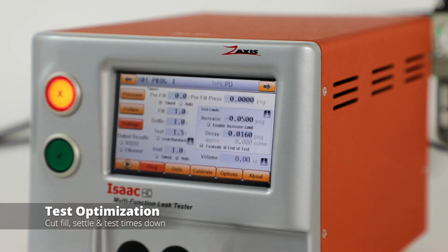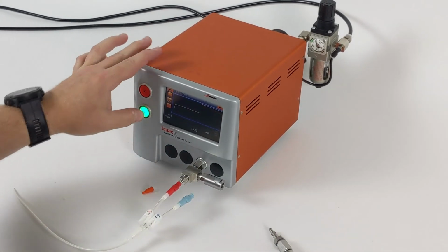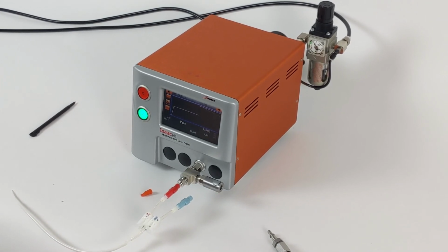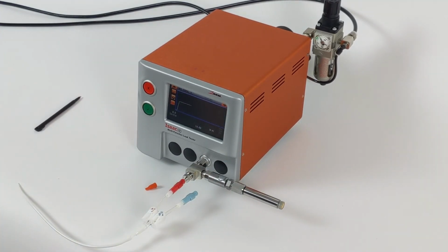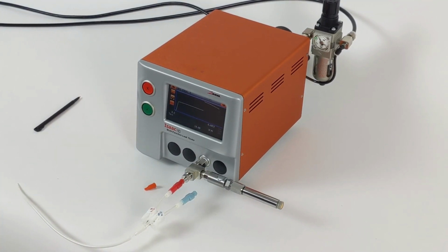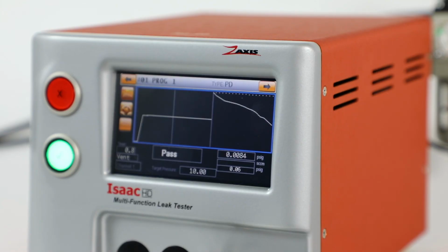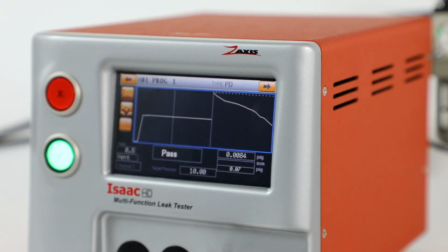We're going to do the same 2 tests again. We're going to take our part, which we believe to be a known good part, and we're going to run it. And again, we get a very small decay value in those times. We run it now with the leak standard attached to it. We'll get a different decay because we're only looking for a shorter amount of time, but do we still have the 3 times separation? In this case, we do. We have about 80 times the separation from a good and a bad.